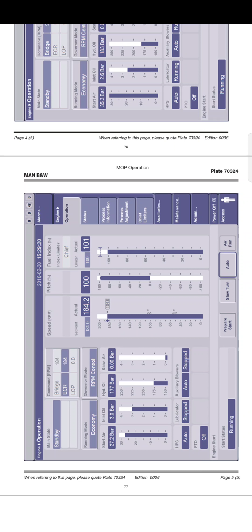If the active control station selection is inconsistent, the ECS keeps the last valid active control station as the active station until a new valid selection is available. In the event the take command signals from both the ECR and the LOP are selected simultaneously, the LOP has the first priority and is selected.